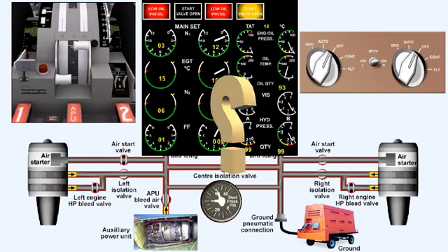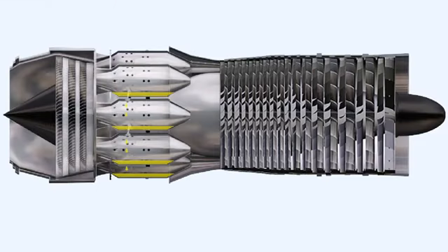However, it may be some time before it's realized that there is a problem, and that the problem is a wet start. Starting malfunctions on gas turbine engines are rare and always come as a surprise, except in the flight simulator, where they tend to become the norm. Thus, there can be a long period during which fuel is being pumped into the engine before the problem becomes apparent. Throughout that period, the combustion chambers and exhaust system are becoming saturated with fuel.